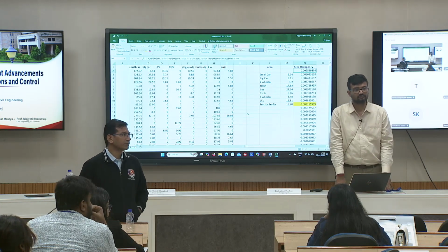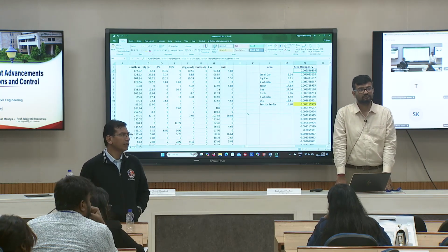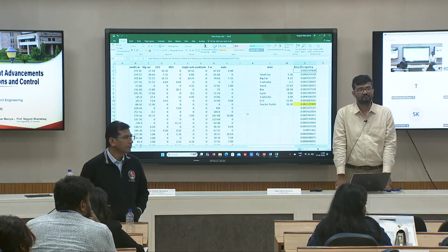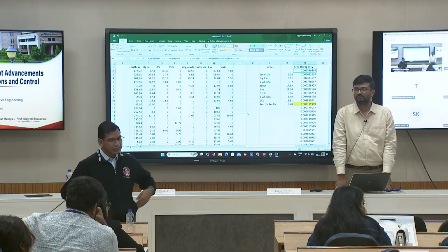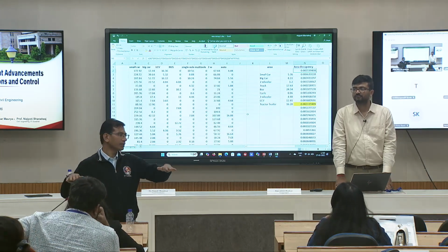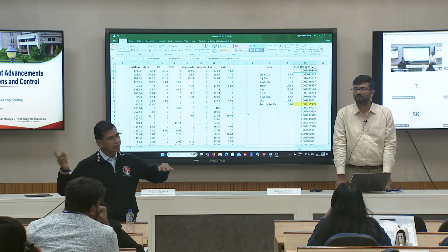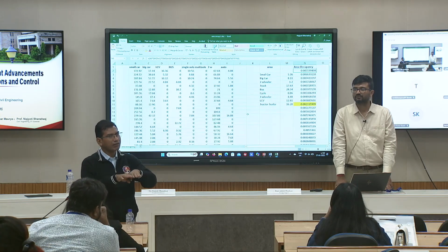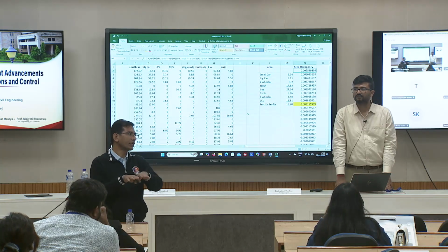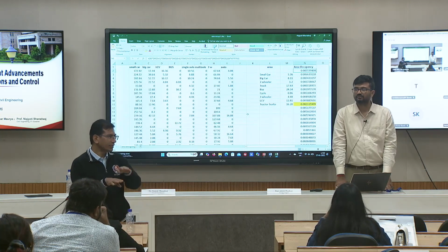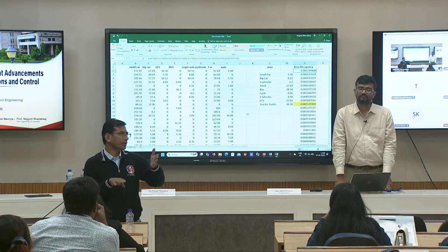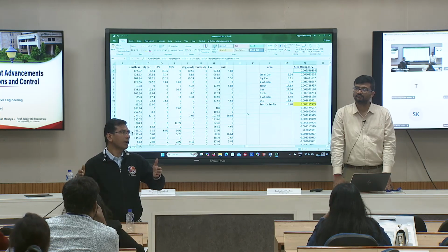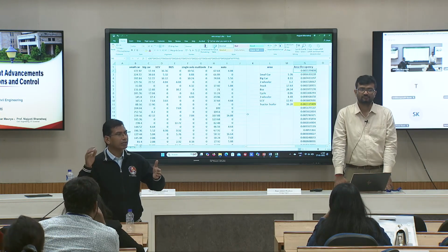Marking will be there after that, and on that asphalt layer two wheelers also used to move in. So this is additional. Earlier, we used to have the other paved shoulder, but with a different material. But there are always issues with the pavement and concrete interface. So that is why this concept came: let us continue the same surface. But most of the time we don't consider that as part of the capacity.